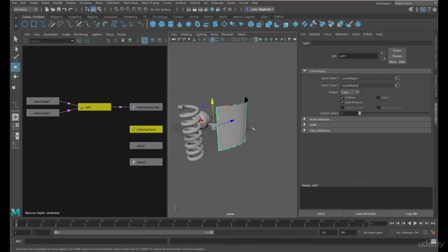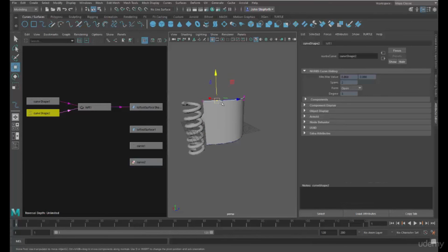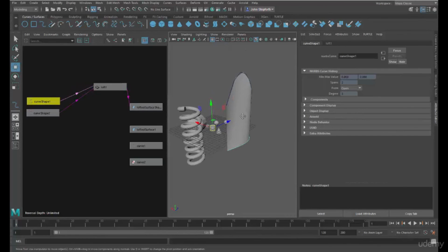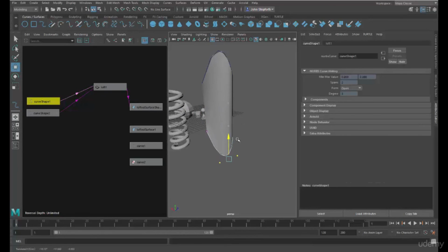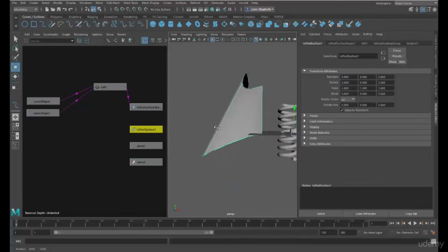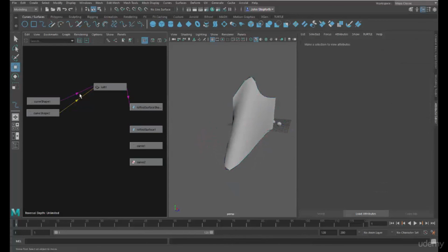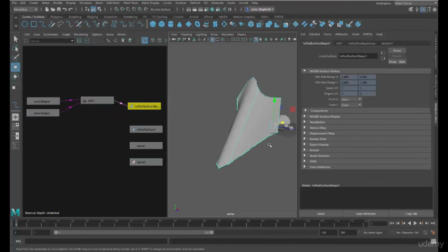And it's when we see how these shape nodes are actually put together, because they're connected. The loft here, this is the loft shape, is connected via these shape nodes. When we modify these shape nodes, we're actually modifying the loft parameters as well. So there's some connected history in there, and you can see the pink lines denote that there is a connection to this surface that we've got in there.